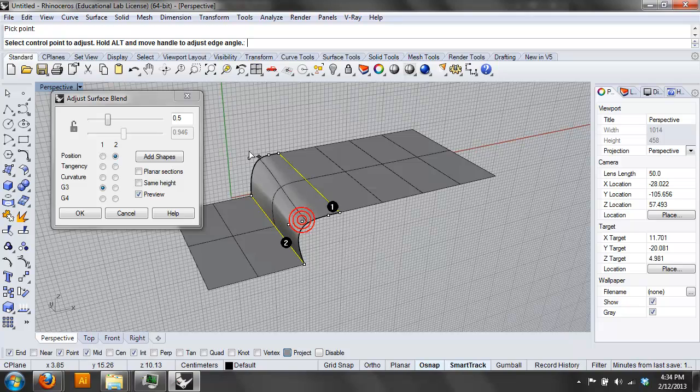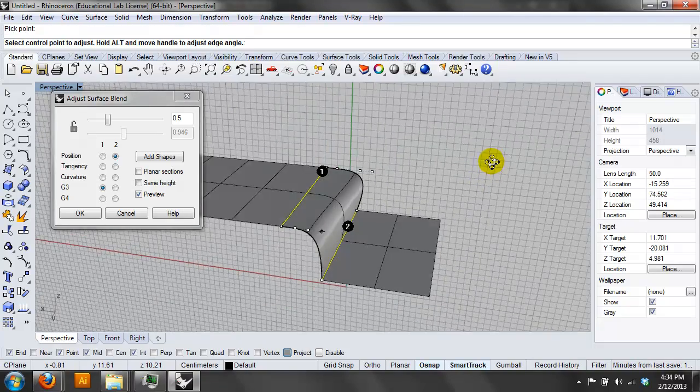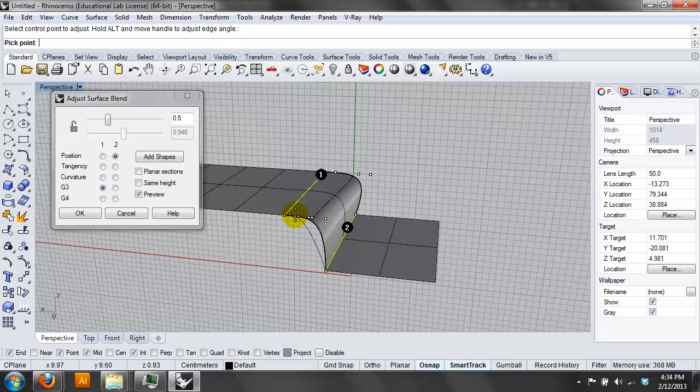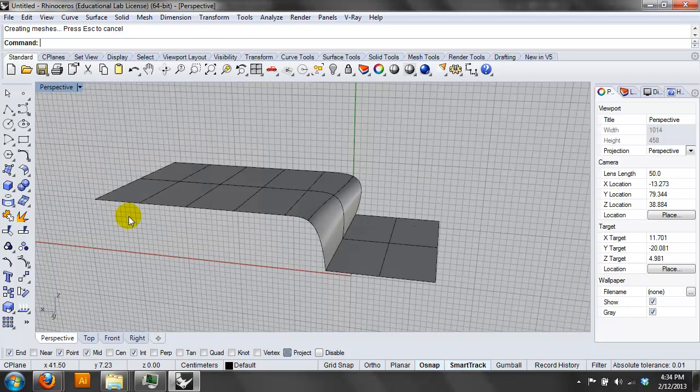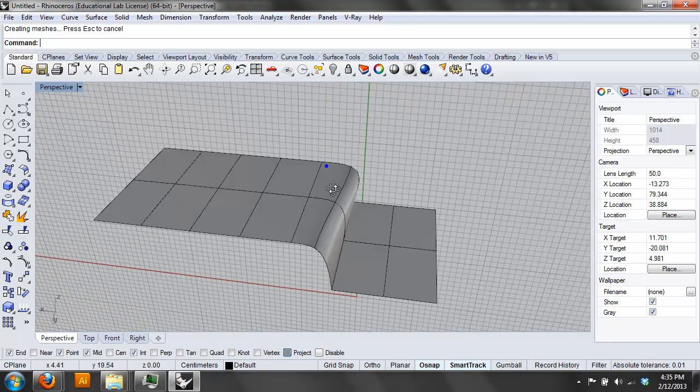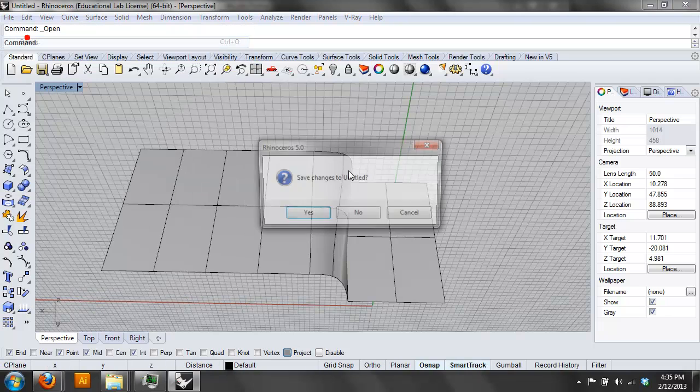Yeah, they give you exacting control, so you can have one that's a little bit more out than the other one is. So blend gives you a lot of nice little parameters that you can actually control, especially in Rhino 5. Some nice stuff here. So it takes a lot of the difficulty. If you were going to do this another way, you'd actually have to draw the cross sections. You'd probably do a rail using the edges with the cross sections, but the blend tool packs it all in the same tool. So surface blends are also your friends here.